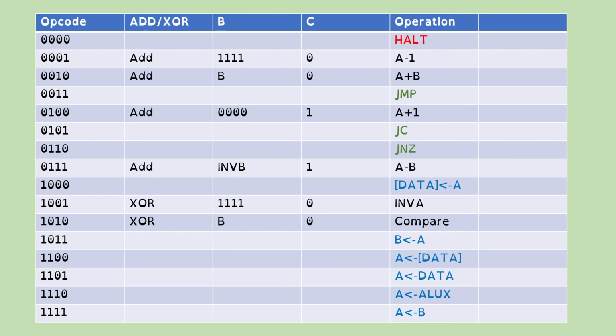The reason for that is because what you tend to do when you put in the opcodes for the program in memory is wipe the memory first, turn it all to zeros, and then you put your opcodes in. And then you don't need to remember to put a halt in, because your next one will automatically be 0. So when you get to the end of your program, it will stop. If 0000 was something else like add A to B, then it'll just keep doing that over and over again. So it's very useful having halt as 0000.